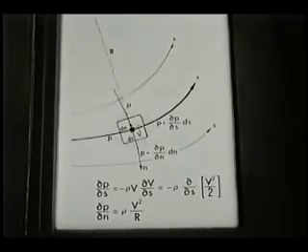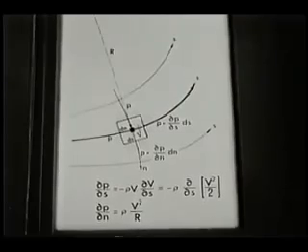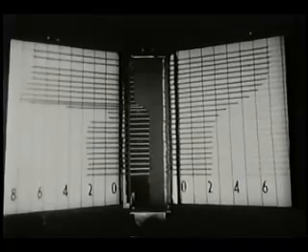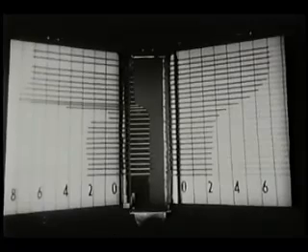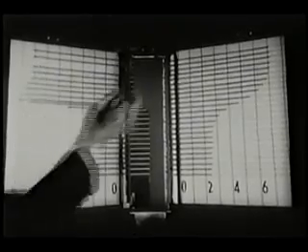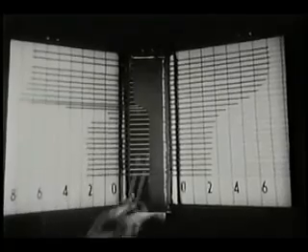Our flexible wall rig now is in the form of half of a rapid symmetrical contraction. Upstream, the pressures are equal on both walls. Downstream, they are also equal, but lower. Because of the area decrease, the average velocity increases, and according to the streamwise equation of motion, the average pressure falls.